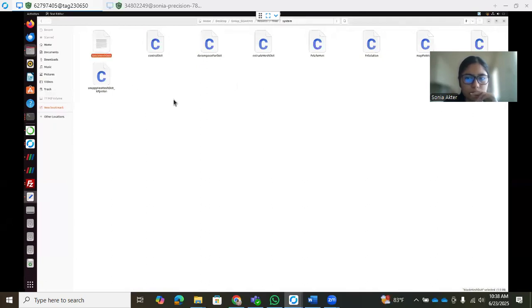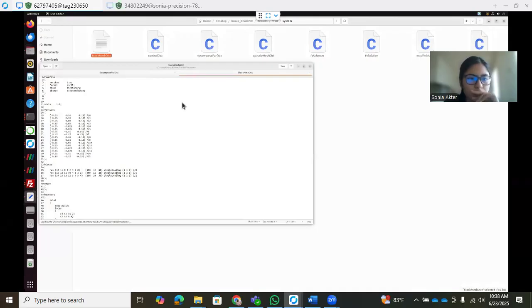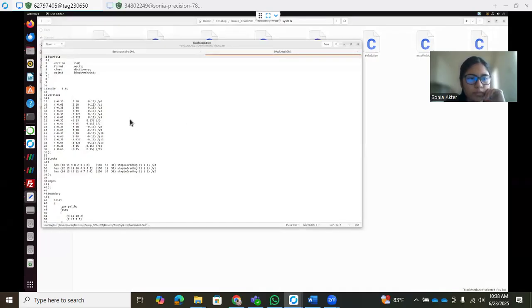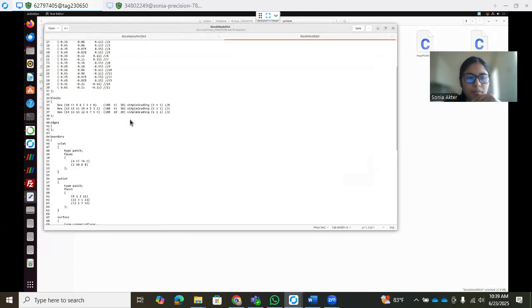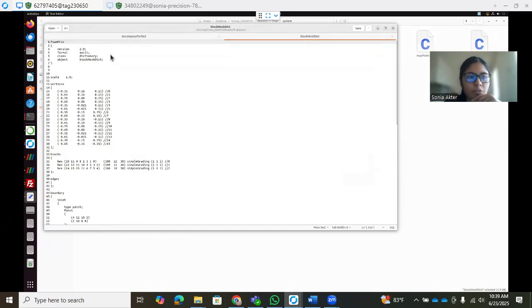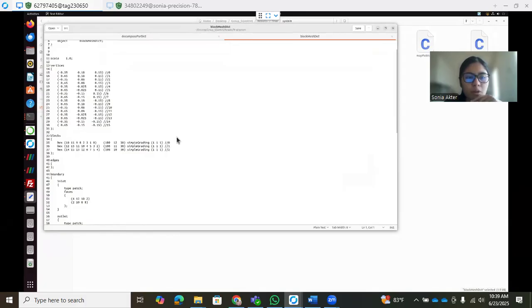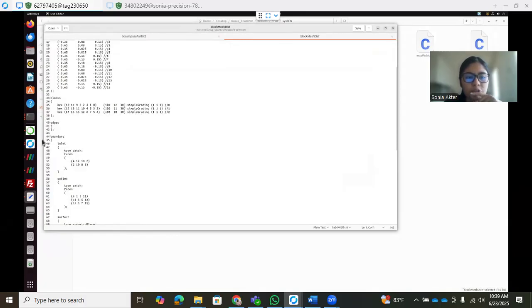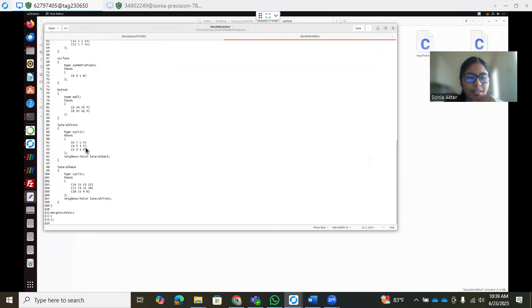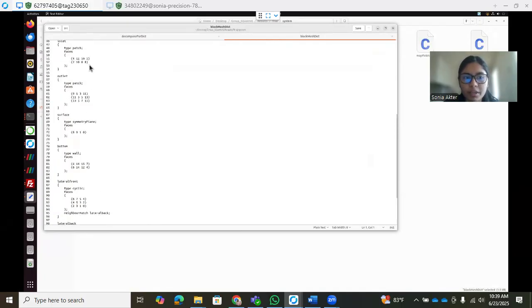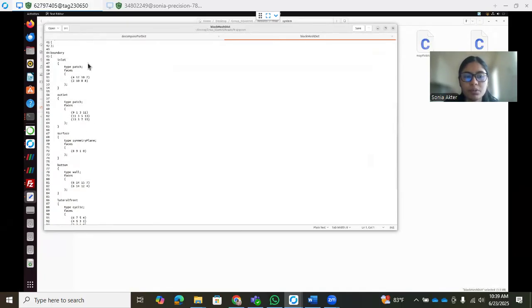yes, this one. So this is the blockMesh file. It has some vertices and how many blocks we are using and which ones we are assigning as the boundary conditions. For example, inlet, outlet, top wall, lateral front, and lateral back. So this is typically the format of using the blockMesh file for creating a simple and easy geometry.